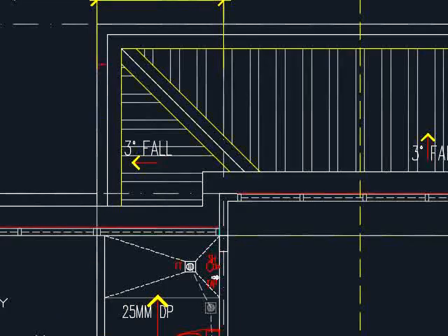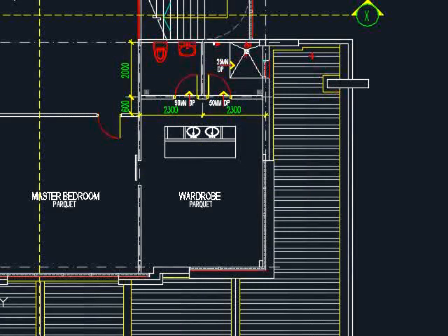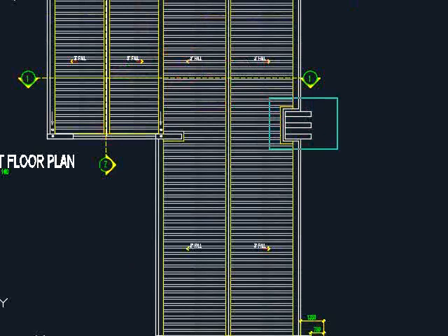As from the first floor level, it should look something like this. That means there is a thickness of the gutter, and this is where the gutter is going to collect the water due to the roof at the first floor level. Be careful with the aesthetic column. Make sure you have those considered in your detailings and design. Same goes to the columns here, as well as the gutters here.